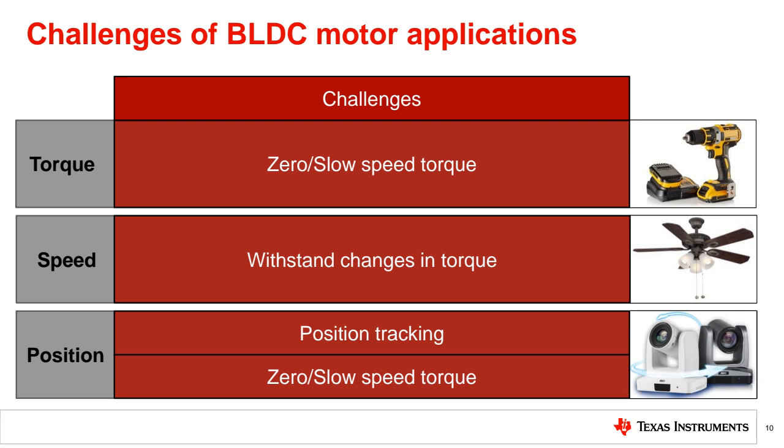So we can say we have a cascade control system here. In the inner loop, we control current. In the outer loop, we control speed. And another outer loop is position. You can imagine inner loop current, another loop speed, and the last one position.